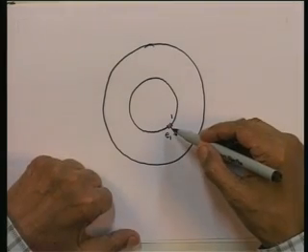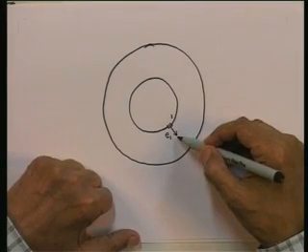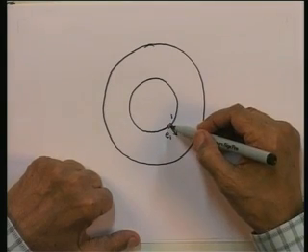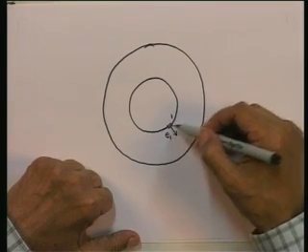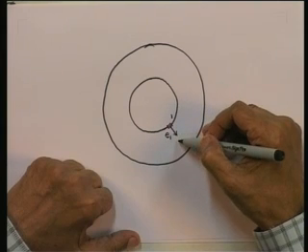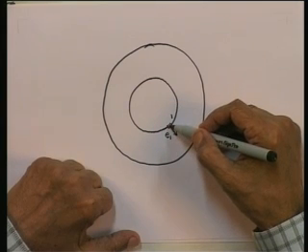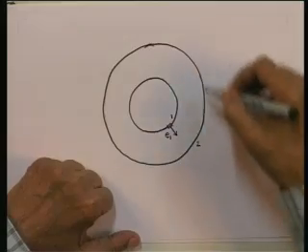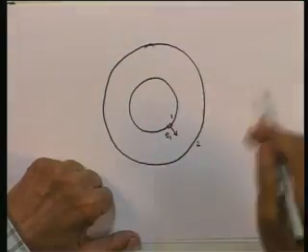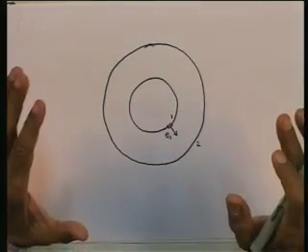All right. Now, this arrow is symbolic, mind you, radiation from this elementary surface is really going off in all directions. So, the arrow is simply symbolic, showing radiation is being emitted from here, and ultimately all of it has to reach the surface 2. Mind you, this is a case in which the surface 2 completely surrounds the surface 1. Therefore, F1 to 2 is going to be 1. All the radiation from any element on 1 has to reach 2.